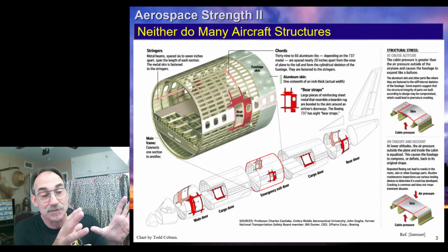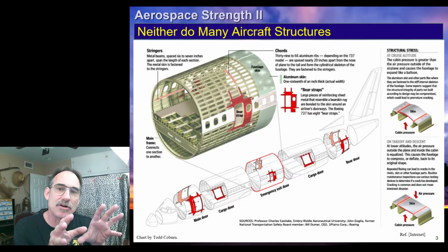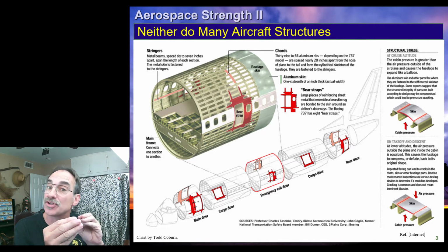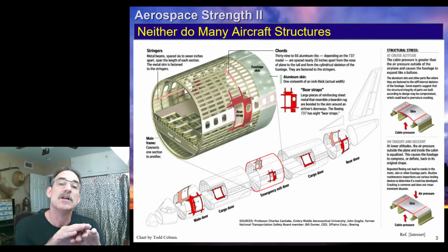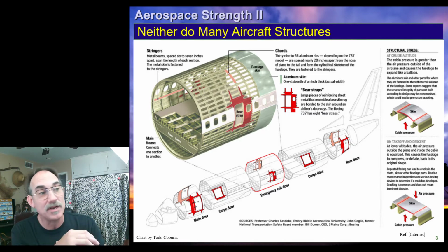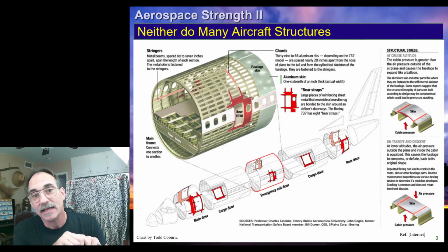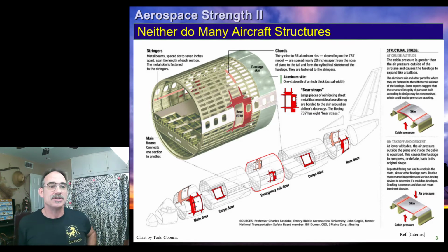If you look at an aerospace structure such as this one, you'll notice that the stringers don't act alone. If one stringer starts to give way or starts to yield or starts to cripple even, it will shed load and share load as its stiffness softens, and the other members, which are unsoftened, will pick up that load. This is true for the stringers and for the frames, for the floor beams, for the window belt, and for many other of the redundant structures that we find in aerospace and other structures.